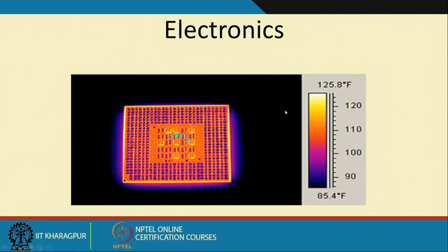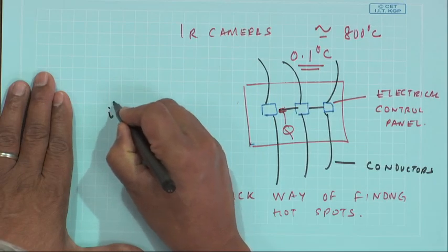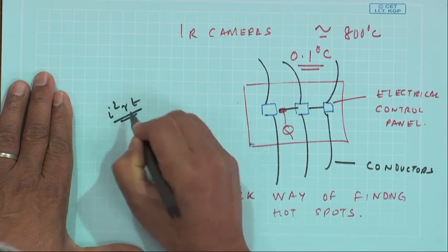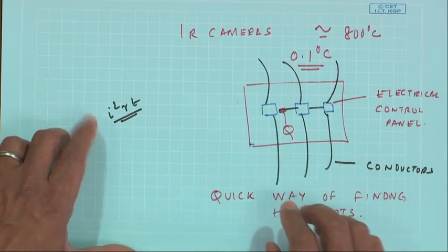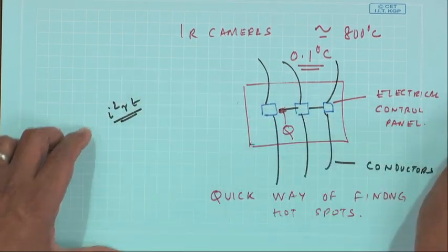Particularly in electronic circuits, if some particular component is not getting power supply, it would not heat. So, you can see some cold spots, and then you can say perhaps this device, semiconductor device or whatever, this IC chip is dead, because anywhere in a circuit I will have this energy depending on the square of the current, and that will be the heat generation.